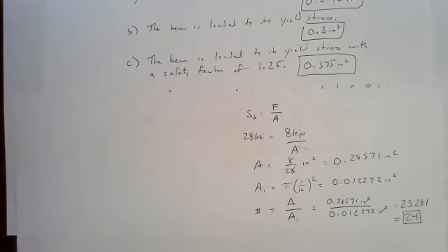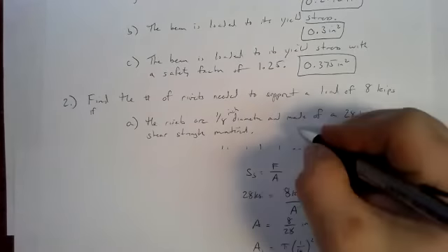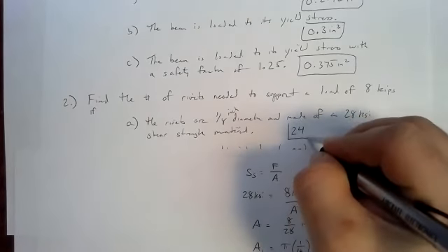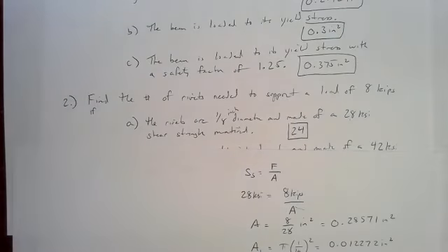So we need 24 rivets to handle that load. So 24 rivets at a minimum. Now, of course, that assumes that those rivets are spaced far enough apart that we don't have structural issues, the stress concentrations in between the rivets, and that they are far enough away from the edge of the material. Other details that we'd have to bring in a real sheet metal lap joint design. But to satisfy the strength requirement, we'd need 24 rivets at a minimum to do that job.